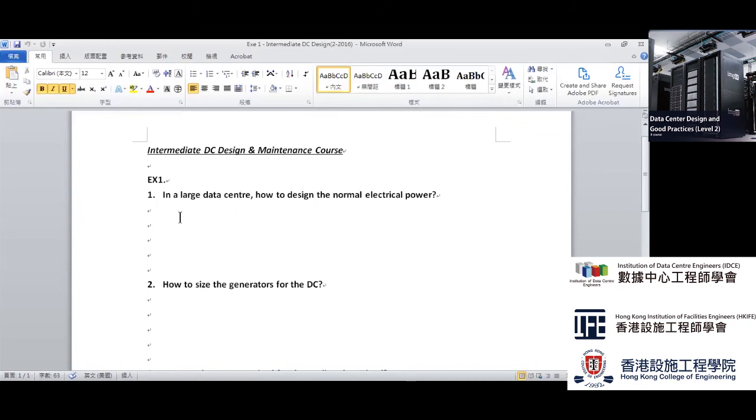First of all, you have to consider the lighting and power, as I mentioned before, right? The lighting and power in the data center is based on something like 15 watts to 20 watts for the lighting, and the power, including the normal air conditioning, you can use either 40 watts or 90 watts per meter square. That's the general lighting and power air conditioning. Lighting for 15 to 20 watts, air conditioning and power usually about 40 to 90 watts per meter square. But